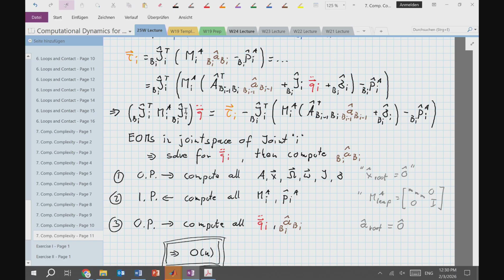It also allows you to reason about questions of design. How large should that motor be? What's the worst configuration? Sometimes it's obvious. If I have an arm like this, that's going to be my maximal inertia at this joint. If I move my stuff in, I will have a much smaller acceleration. But it may not be that obvious if you have other things happening, like unconstrained or loosely moving joints. So what's the inertia if I do this, without keeping my arm fully extended?